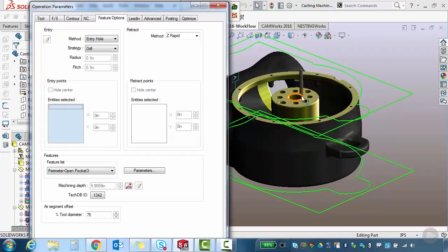So if I come out here, I can pick that I want that to go in the arc center. You'll notice I just highlighted it and then clicked it in SolidWorks. And then I can also tell it, well, I want it to come out of that hole as well. So real quickly and easily, if you were machining and you'd already drilled all these holes and you want to come back and finish it, you can tell CamWorks, hey, start in this hole, come out of this hole, and instead of doing a feed in, feed out, you have the ability just to drop in.